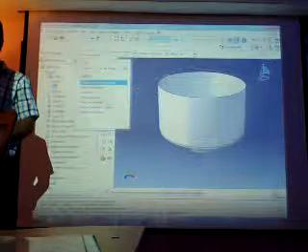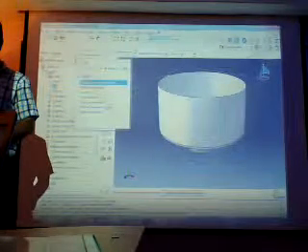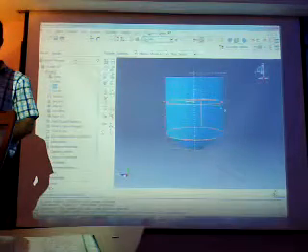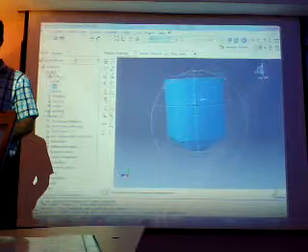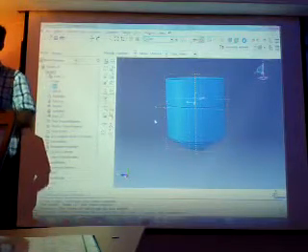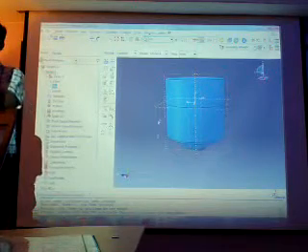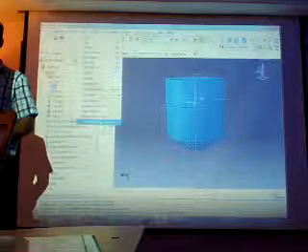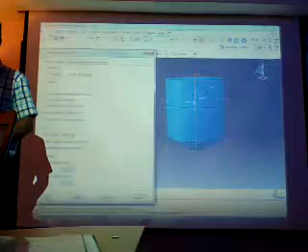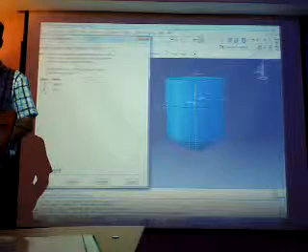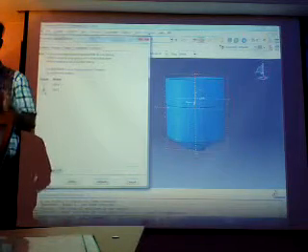Take x set and go back to the assembly. One of the problems in Abaqus is that now you cannot recognize which plane belongs to which part. From view, assembly display option, in instance, you can hide and unhide your part for easy assembly.